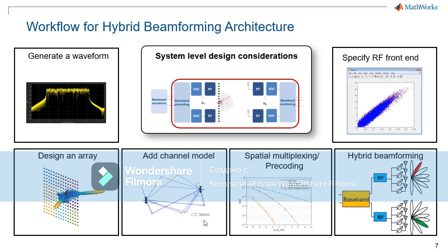And if you are doing high beamforming, you also have to consider the analog beamforming parts, those elements that use phase shifters in order to essentially steer in the analog context without using all the RF chain to steer your beam in another direction. And after all of that is done, you have to consider the effect of the RF front end, the amplifiers, the filters, and so on, and make sure that within your bandwidth of interest, the amplification is linear. Otherwise, you suffer a lot.